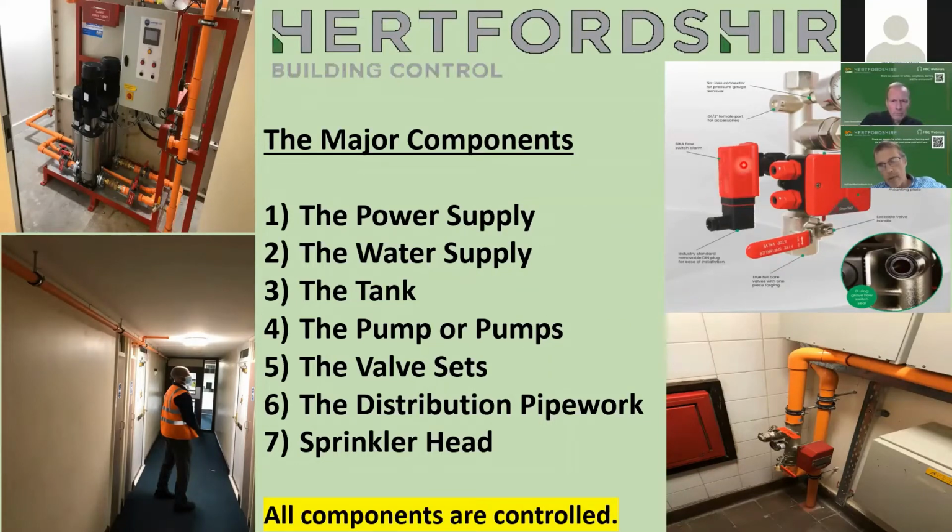That fella there's the flow switch. So the second that a sprinkler head goes off, water will flow through there. That switch will then alert, that interface on the flow switch will alert the fire alarm panel. That's the gauge. So keep an eye on that and make sure it's design pressure at that particular point. And that fella there's the drain valve. So if you want to drain it down.